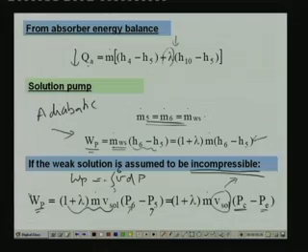The power input to the solution pump, if you remember, is negligible compared to the heat input to the system. That means in the COP calculation you can neglect the solution pump work, but still you have to calculate the amount of work required by the pump, because when you are designing the system you have to select a suitable pump and motor. That means you have to specify the required capacity of the motor. For that purpose you have to know the work input to the pump.